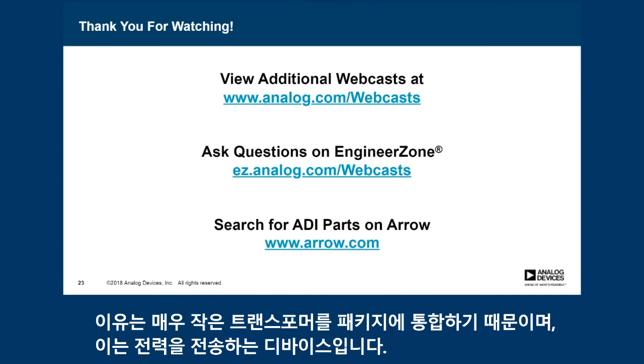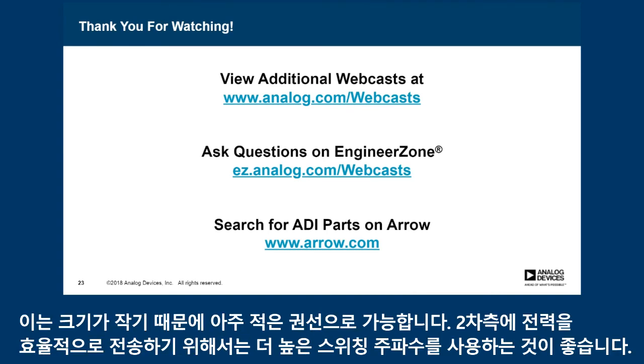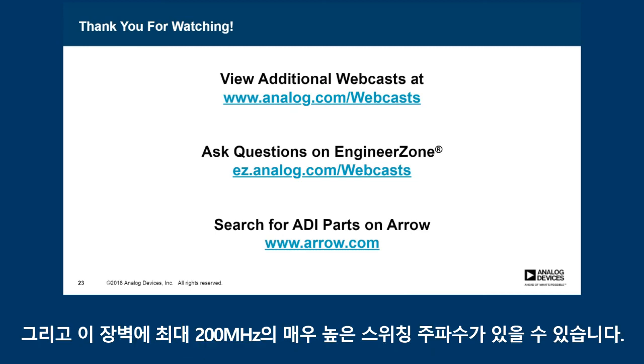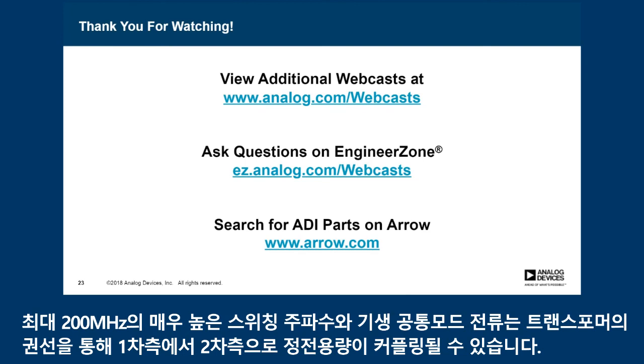Well, the reason is that we are integrating a very small transformer into the package, and this is our power transfer device. Because of its small size, it only has a few windings. That lends to the need to go to a higher switching frequency to efficiently transfer the power to the secondary side. An ideal transformer driver would be purely differential, but because of small mismatches that exist, there can be some common mode currents present that go across the barrier. And with these very high switching frequencies, up to 200 megahertz, the parasitic common mode currents can capacitively couple from the primary to the secondary side through the windings of the transformer.